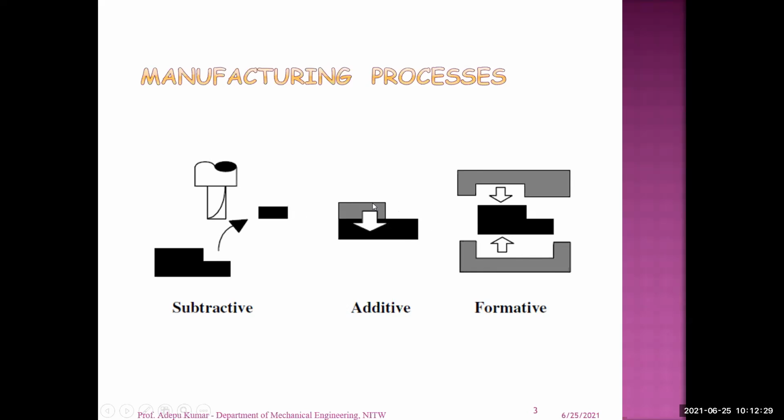Why don't we generate this component through an additive manufacturing facility? Yes, it is possible. What I do is deposit layer by layer according to our predefined geometry, which is developed through a CAD environment. Then based on the CAD model, you generate the component by melting powder particles or supplied wire, or a combination of these two in the latest technology, or otherwise you can add even solid material one over the other so that it becomes your required geometry.